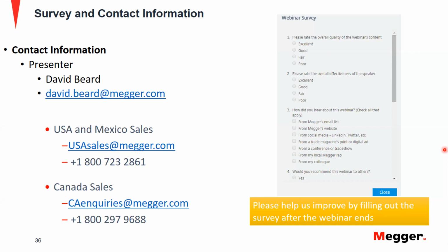What it does is it provides the value of phase. Let's say you're testing phase A. It would provide current value on phase B and phase C such that the zero sequence current turns out to be 0. So you can increase a phase value, but in the similar way, you can actually keep the zero sequence current to be 0. So your 51G would never pick up, but you can test your 51P. So that's how you do the testing using symmetrical component theory.